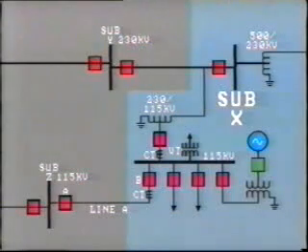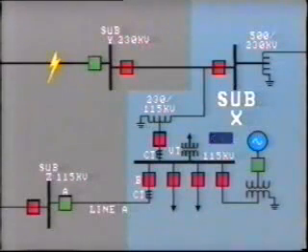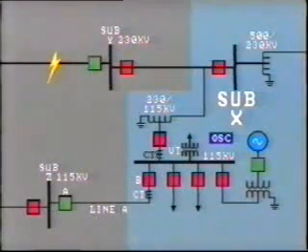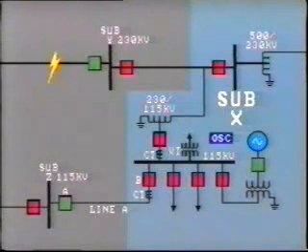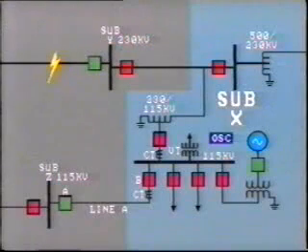Breaker A at 115 kV substation Z trips for a remote fault on the 230 kV system. With the help of the oscillographs located in substation X, we were able to spot the problem and correct it. In substation X, the oscillograms monitor the transformer breaker's A-phase current and the zero-sequence residual current. Also monitored are the 115 kV bus voltages in all three phases, as well as A-phase and residual current for breaker B connecting to substation Z.